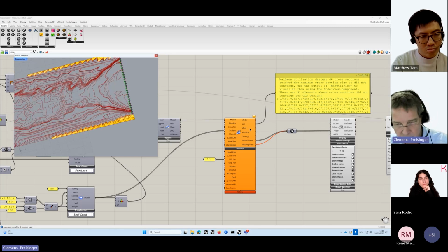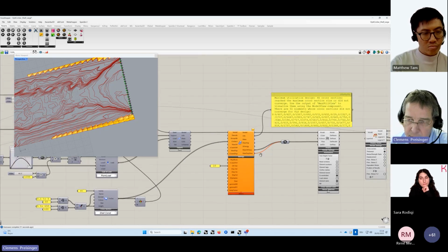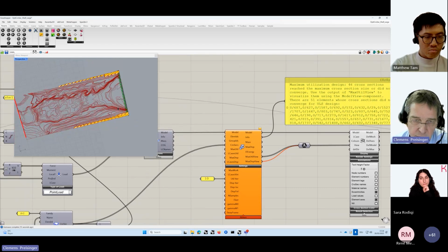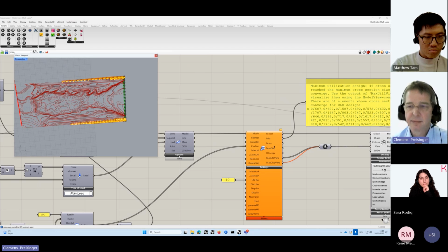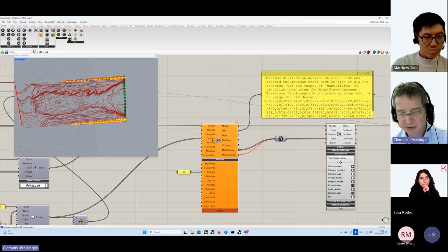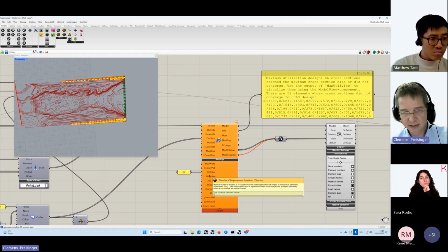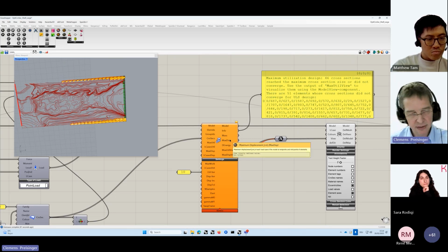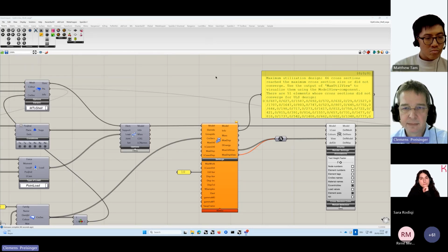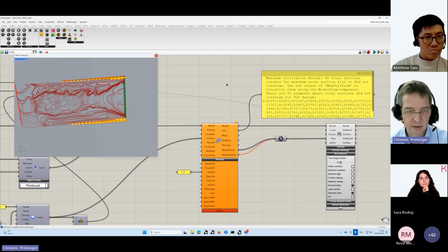By the way, we will improve this optimization component further in the future to make it more versatile. Because at the moment it gives you this warning, although the design is probably okay. The reason is that the optimization is an iterative process, and so if after like 10 iterations there are still changes in the structure, you get this warning. Although in case of a plastic material, like for example steel, the design would be okay nevertheless.